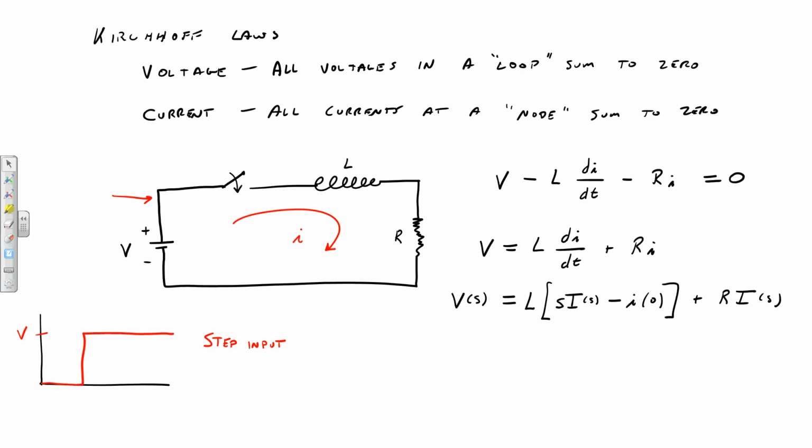But if you model a step input with the Laplace transform, you remember how they set up the Laplace transform with the Laplace integral, and you go over that all, right? If you do that, you actually get a 1 over s. I don't know if you remember that. But every time you have a step input, you actually have a 1 over s in the Laplace domain, okay?